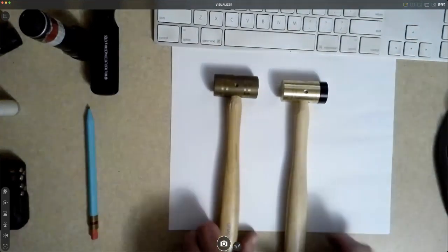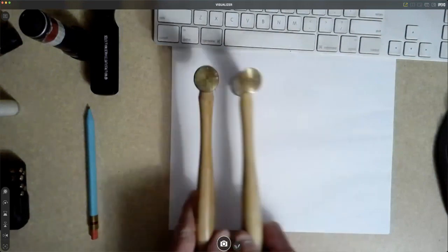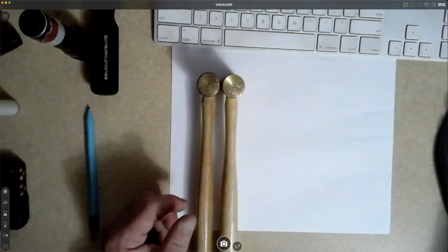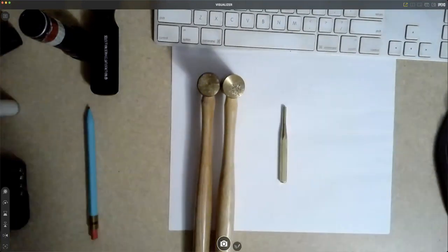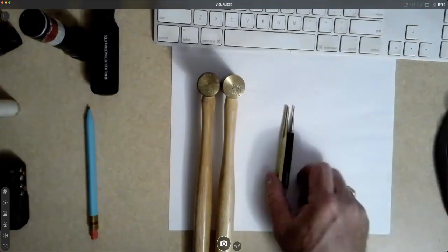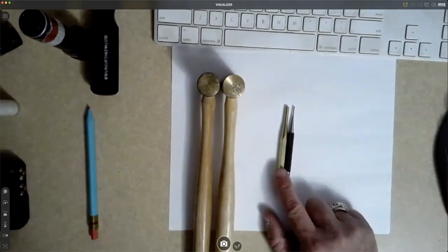And just like steel versus brass has its own things. The reason why we have brass punches is, again, to try and not mar whatever the surface is. Correct. So if you don't have a sight pusher and you're going to drift your sights, always drift them with brass. The brass. Okay.